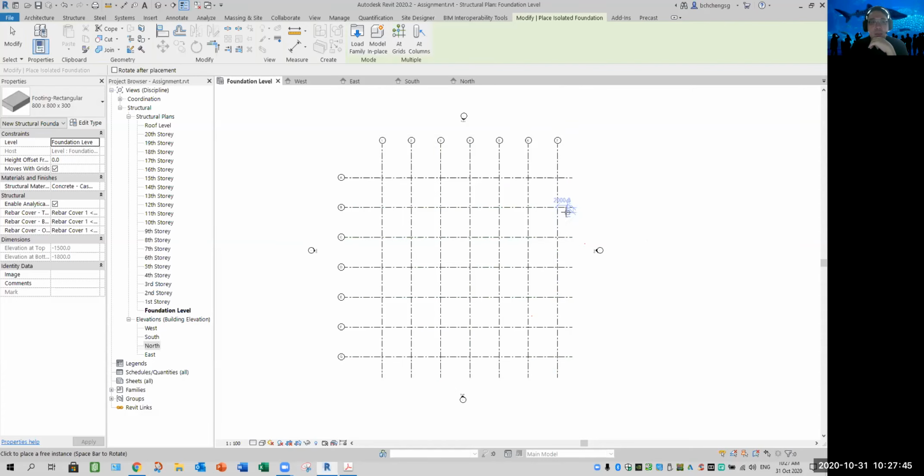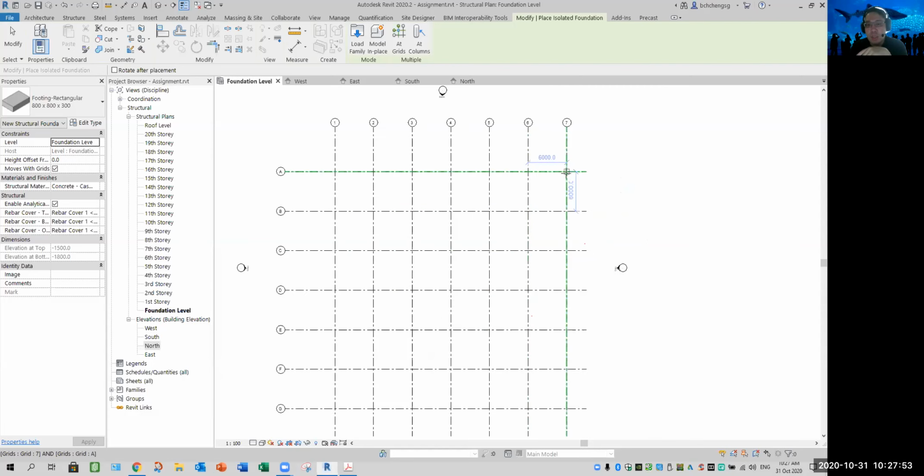Before you insert, normally when you insert, it should be in the center of the grid. But if you pick one by one to insert, it's going to be very slow. In Structure, when you pick column, beam, or footing, you notice the command always has At Grid and At Column, meaning the component can be inserted at a column.